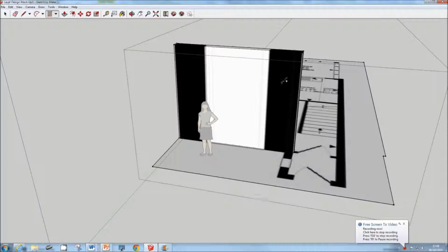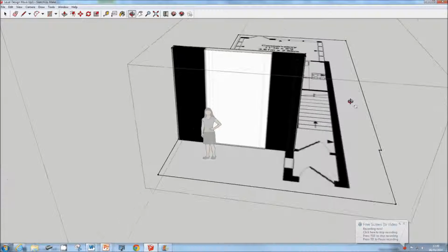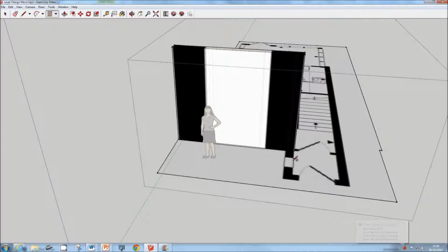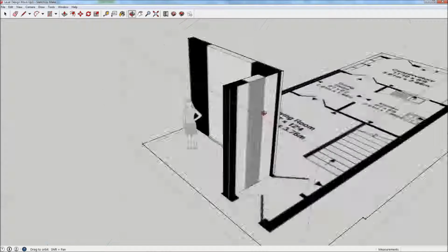Okay, so the next stage is to project a wall from this first initial wall. So we'll project this wall off around the main doorway here. So basically, just referring to the plan, we draw off another rectangle that takes the plan as its reference point. So we draw the rectangle on the face of the existing wall, then back to push-pull, and then drag that wall out so that it projects out from that initial wall.